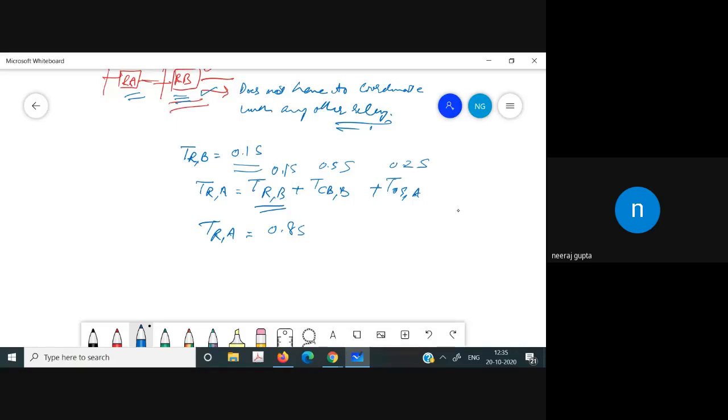So it means that the time setting between the operating time of two relays is equal to the sum of the operating time of the circuit breaker at B and the overshoot time of relay A. And this is essential for maintaining the selectivity between A and B. So it is also known as the selective time interval, that is STI.